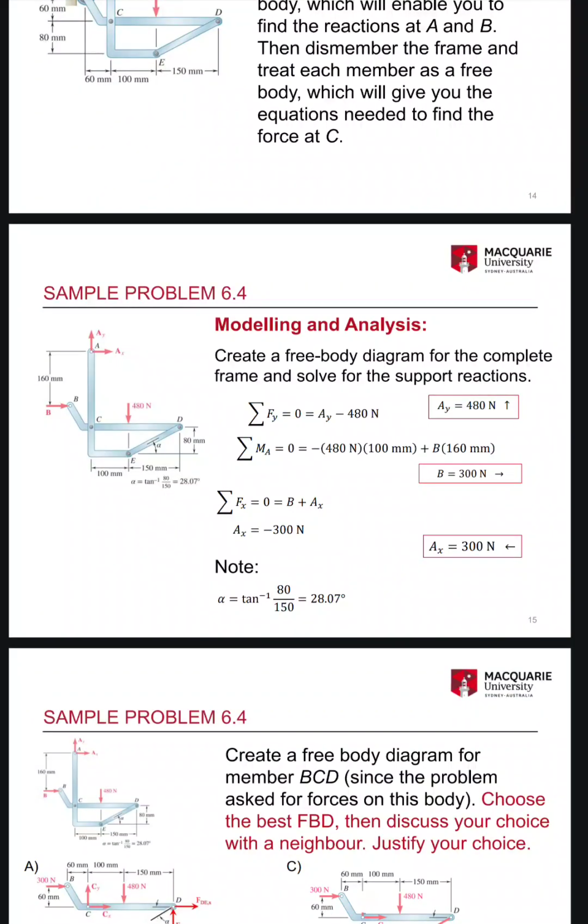6.4 Modeling and analysis of the problem. We can say alpha equals tan inverse of 80 by 150 equals 28.07 degrees. Also create a free body diagram for the complete frame and solve for the support reactions. Sum Fy equals 0 equals Ay minus 480 Newton. Ay equals 480 Newton going upward.